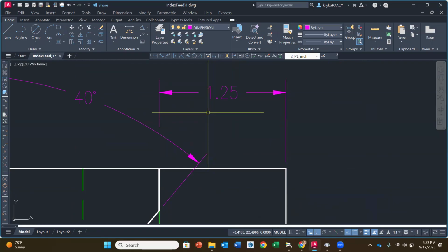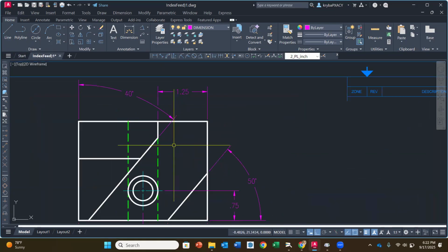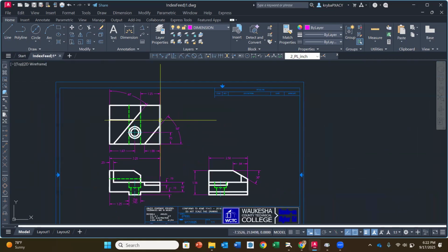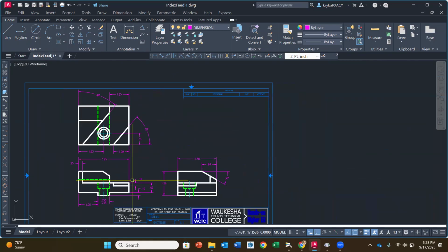So now what we have to do is we just have to add a line that's on the dimension line layer. So I'm going to add a line. I'm going to activate that endpoint, create a gap, go straight up, and create that gap. That's it. Okay? That's what you have to do. Make sense? Because again, we can't cross a dimension line. Dimension line is the one that has the arrowhead on it. All right. So I think we have all of our linear dimensions in place.